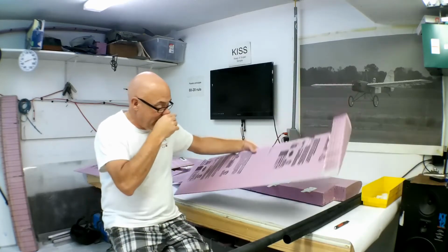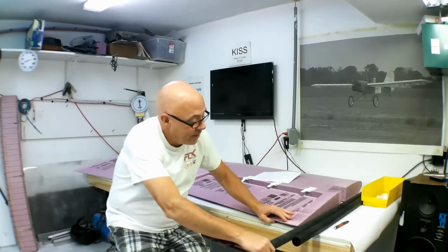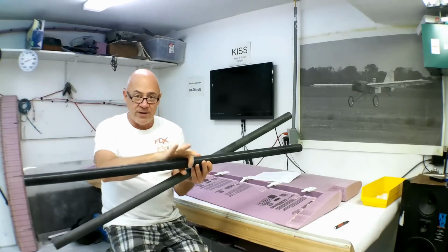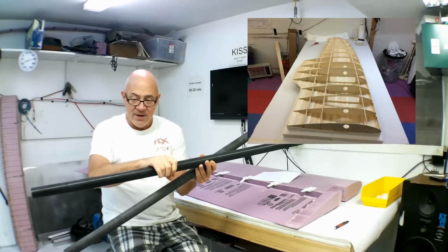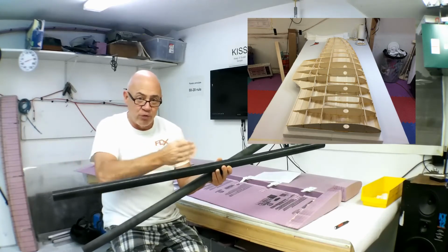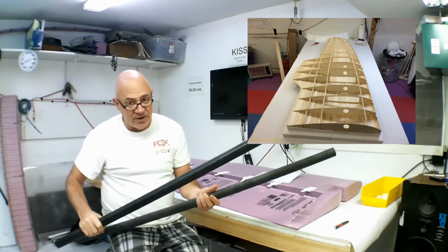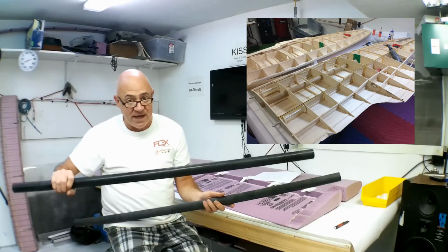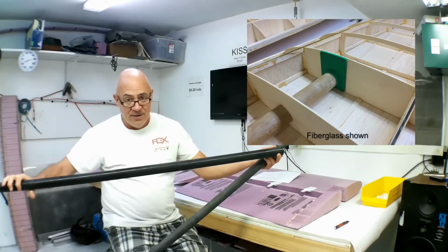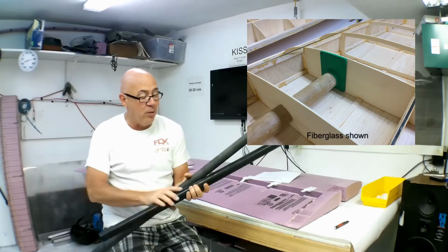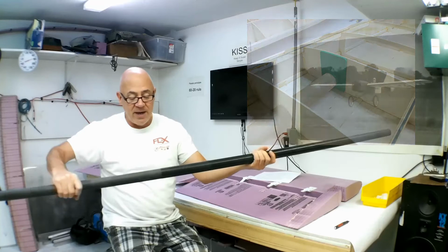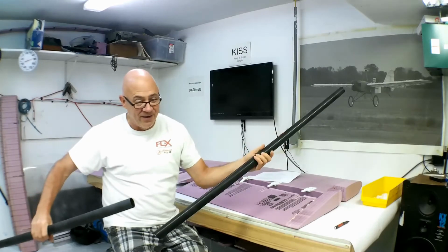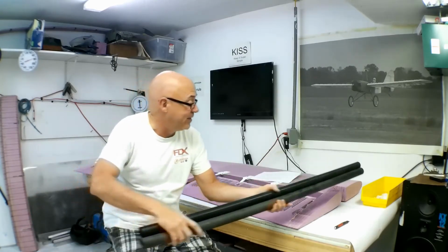If it's a built-up wing, and built-up wings are more complicated, you're going to take this socket, and it's going to be placed inside the wood ribs inside your wing and epoxied so that this is held in the ribs. Now, I kind of cheat a little bit on a built-up wing. Because this is carbon fiber and not phenolic tubing, I will run this out to the very last rib I can get. And this becomes kind of a sub-spar. Even though my wing socket, my wing tube, might only go into here, the rest of this is still pretty strong. And it doesn't weigh hardly anything. So that's how I build wings really, really light.